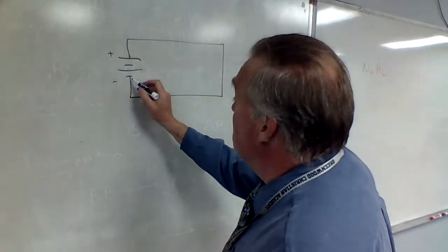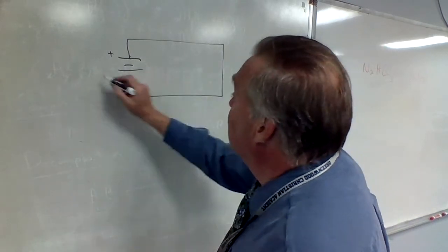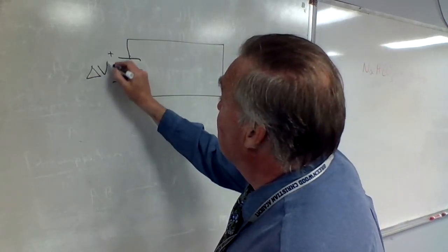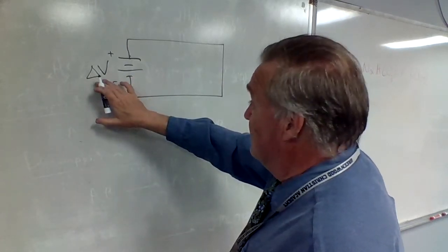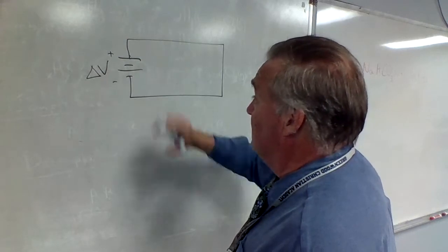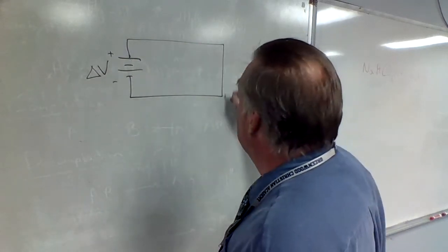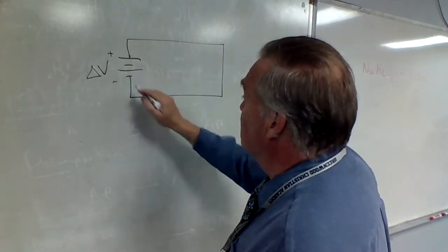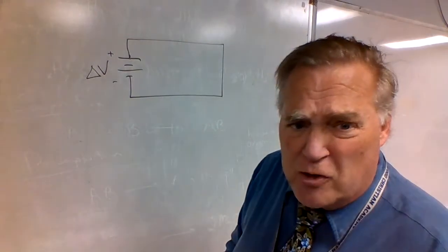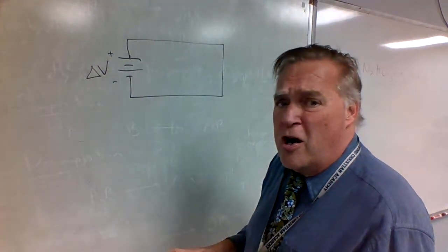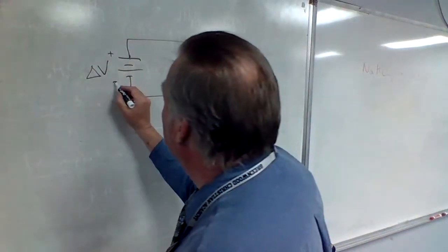electrons actually move from the negative side of this, this is an electric potential, okay? A battery, a car battery, a 12-volt car battery, for example, okay? And you hook from the positive post down here and to the negative, which is the negative side of the battery. It's also hooked to the ground of your car. So your car is the same voltage as the negative side of this battery.